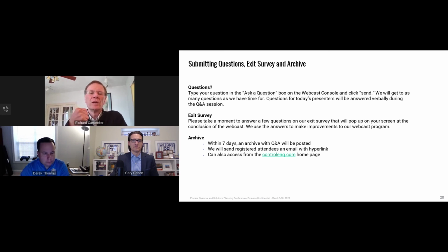So bring it in from an industrial device and immediately route it to MQTT. That's one difference. The second difference is the incorporation of advanced analytic tools, like we talked about Grafana and Node-RED and Python and others that are part of the edge device, to take that data once it's been acquired, analyze it, and provide some insights to customers. Incorporation of dashboarding tools so that that information can be made visible to operators. So I would say data collection, data acquisition is just one component of an edge device.